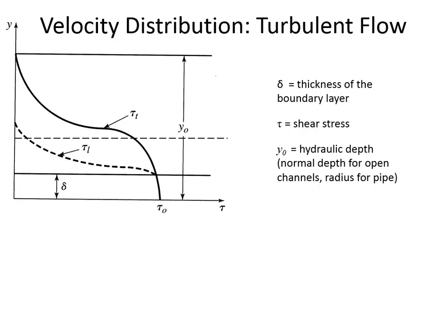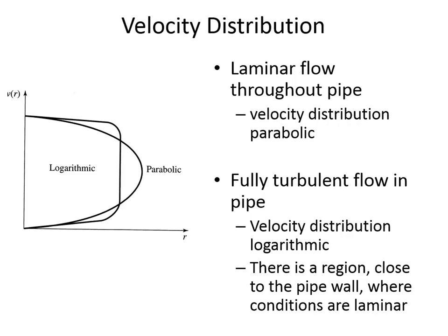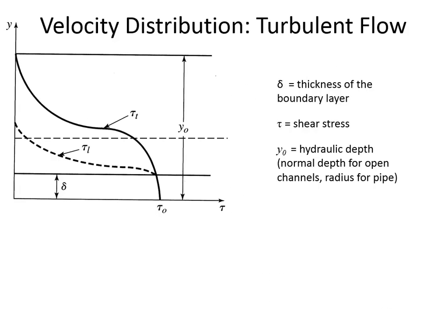This is a little bit harder to visualize, what's going on in the water. So we're going to spend a few minutes talking about boundary layer thickness. This is at the edge of the pipe. We were just talking about where the velocity is high and where the velocity is low in the pipe. The velocity is fast in the center of the pipe. The velocity is slow at the pipe edge. Now, what does that do to the Reynolds number? Remember, Reynolds number is a function of the velocity, the diameter, and the kinematic viscosity of the fluid.